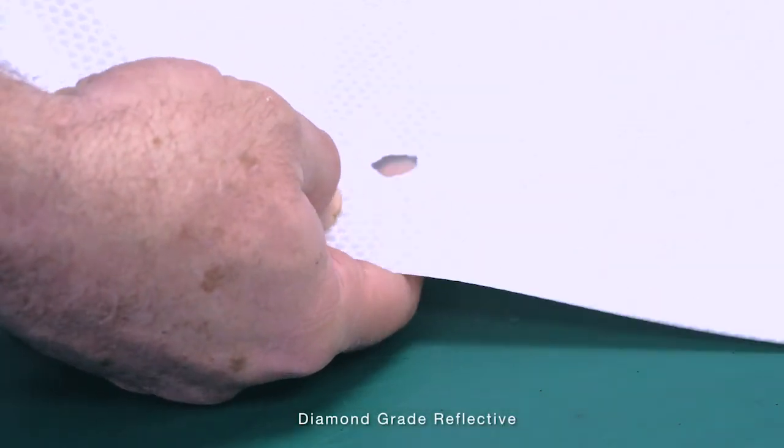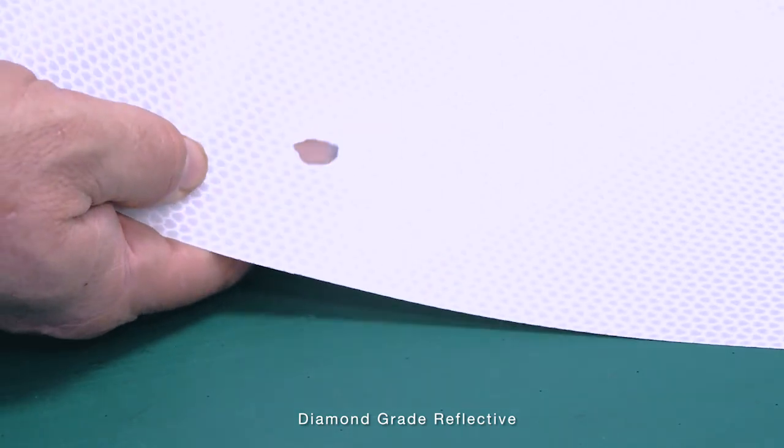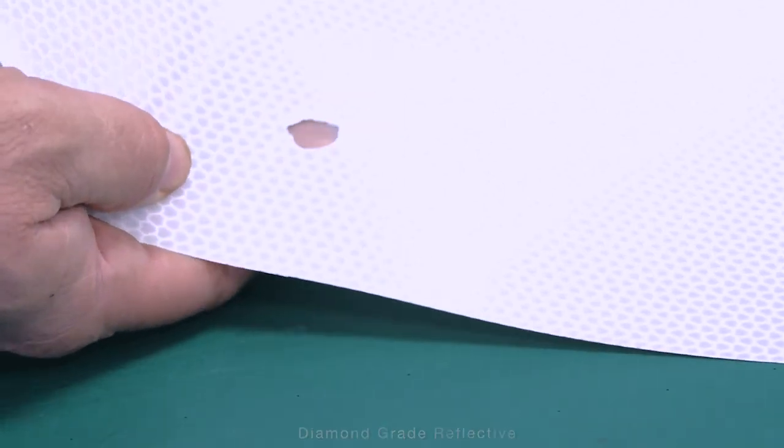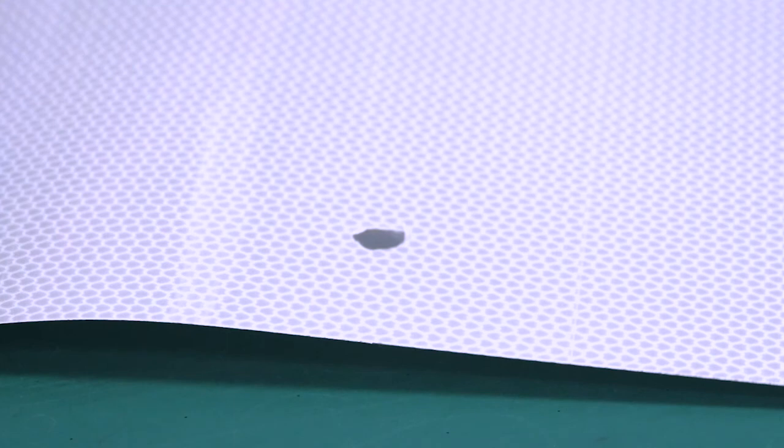If you plan to cut media with a carrier or backing, such as vinyl or sandblast, reach on the back side of the media or vinyl, and with your hand try to push up from the back side of the media under the cut circle. If it pops out easily, then the blade is extended too far.